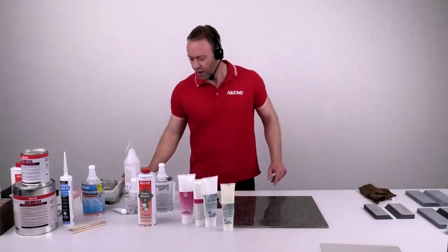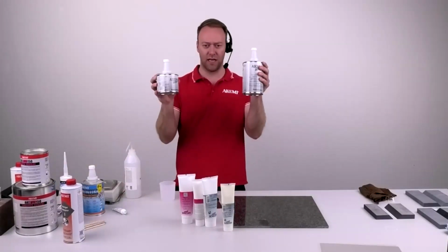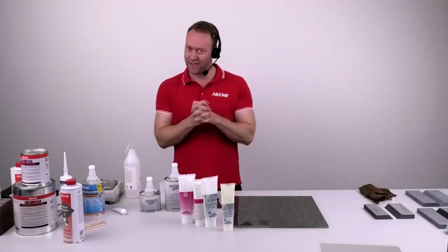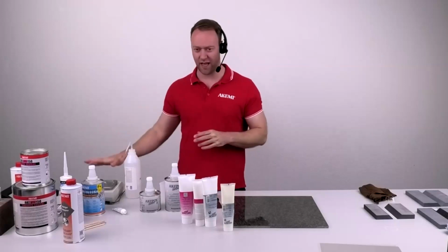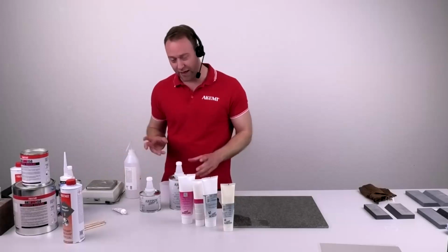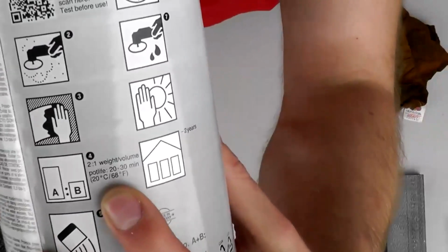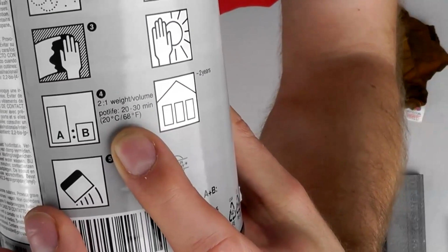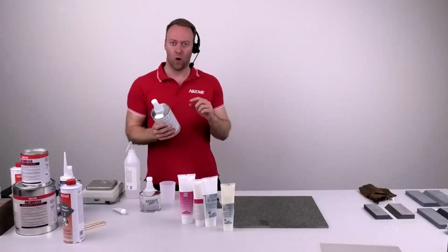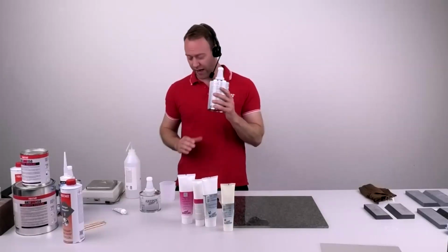Exactly. Okay, so cans, this is Akepox 5000, a liquid epoxy, 2:1 mixing ratio. Usually we say you have to weigh them with a scale, weigh your 20 gram and 10 gram, for example, in some cases, but then you have to check what is written on the can. If it says per weight or volume, then the density of the product is 1:1, like 1 gram per cubic centimeter. So in this case, you can use, for example,